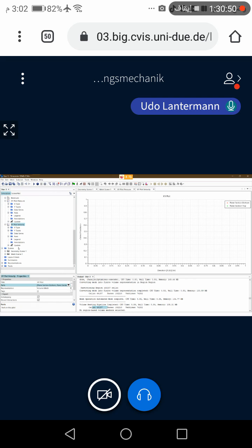Okay, so scenes we can create also after the simulation. So maybe we will start our simulation. So how to start it? At first, you have to initialize your fields. This will be done by clicking on this green flag. If you click this once, then it's written initialize solution is finished. And after it, you can start.